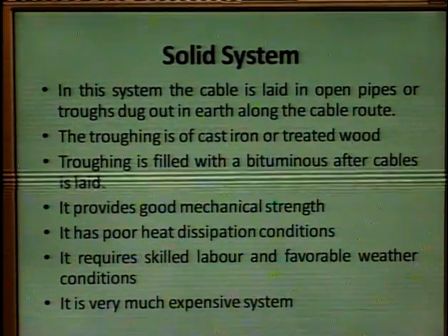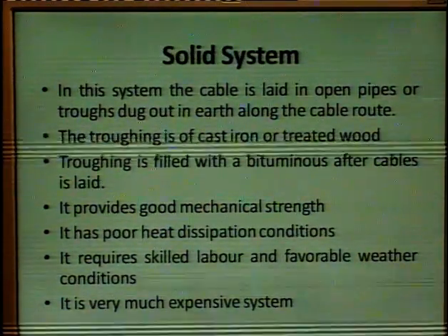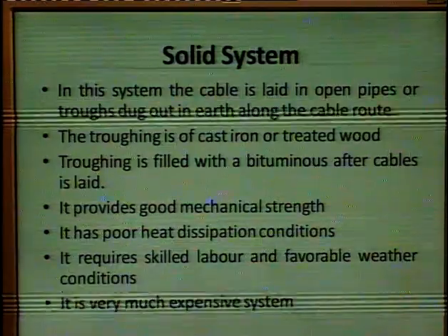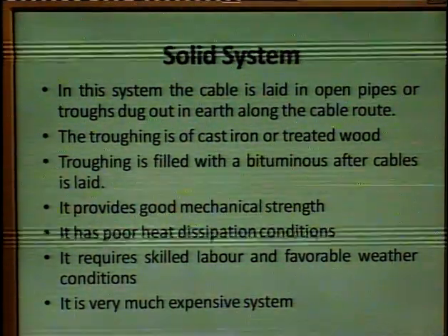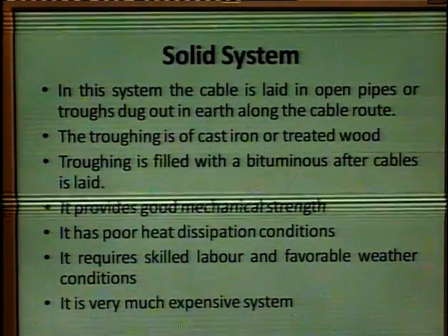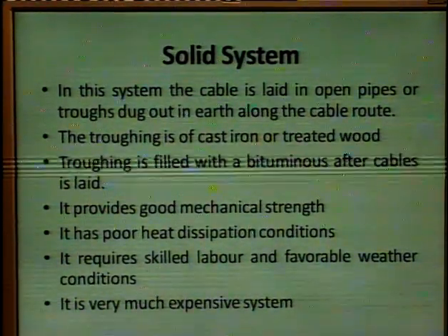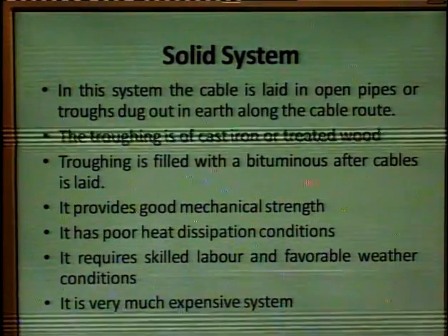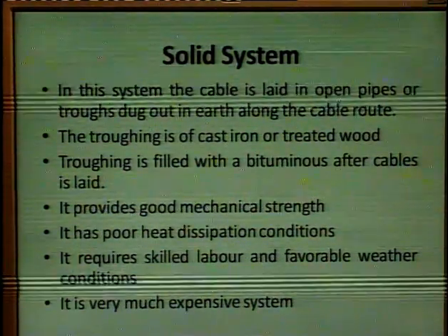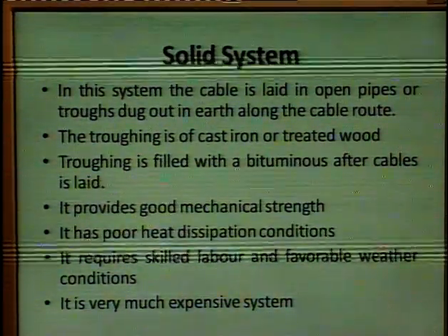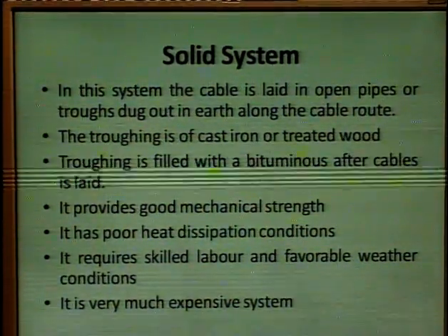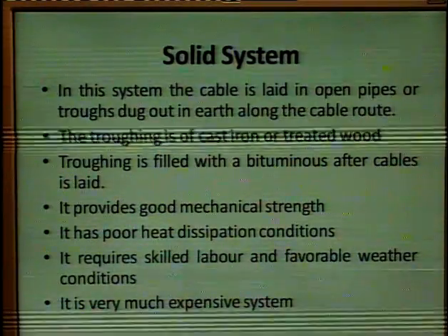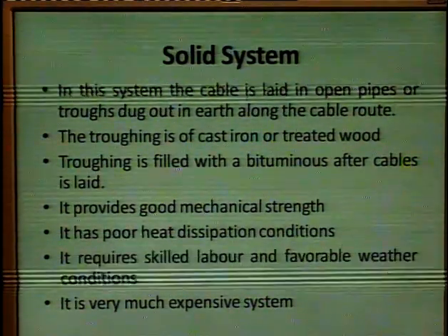The troughing is of cast iron or treated wood, and this troughing is filled with bituminous material or concrete after the cable is laid. It provides very good mechanical strength, but the heat dissipation conditions are very poor.